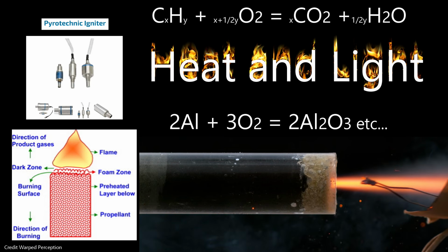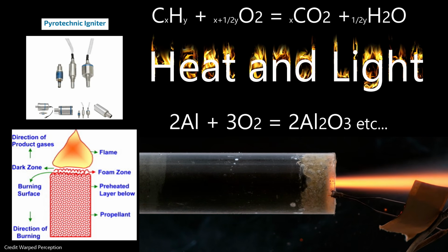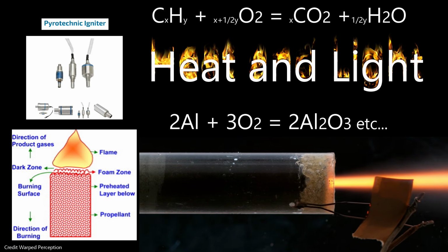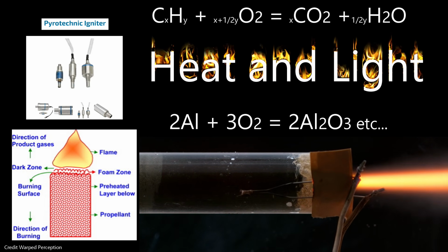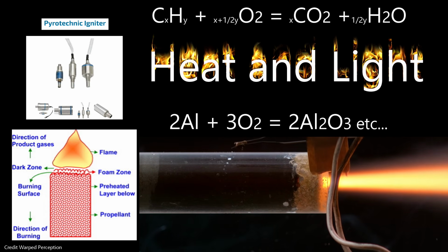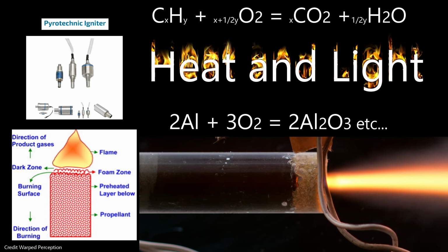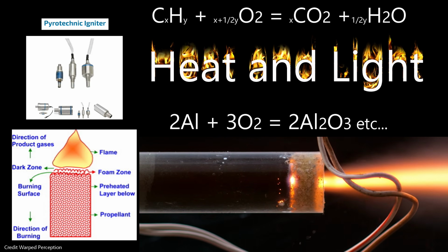This produces a lot of heat and light. The solid materials are vaporized by this heat and light and go on to recombine again, and you get a boiling porous reaction zone, sometimes called the fizz reaction zone, which can be visually observed on the propellant surface. The hot gases exit your rocket motor and your rocket flies.